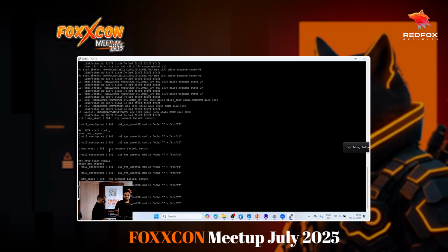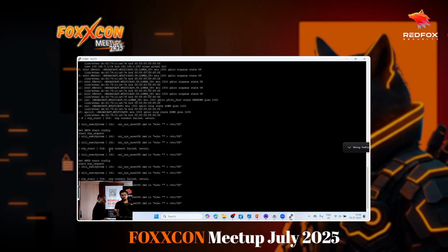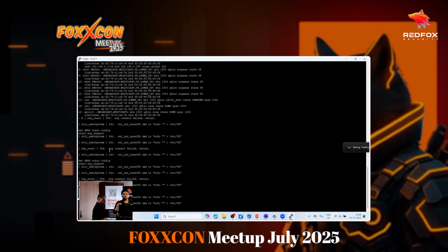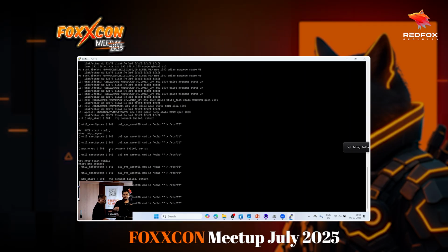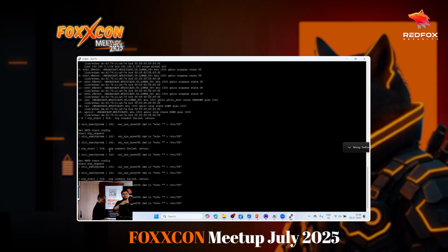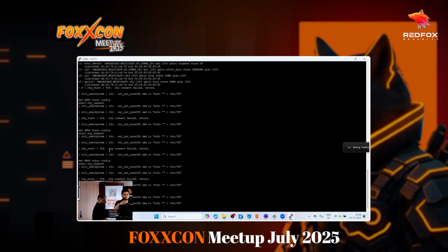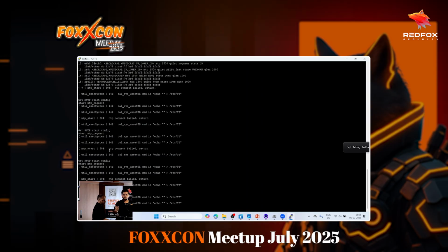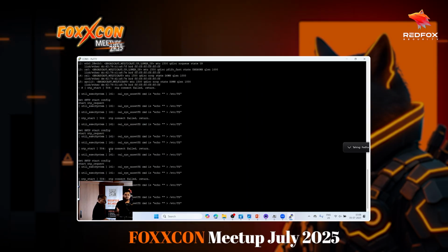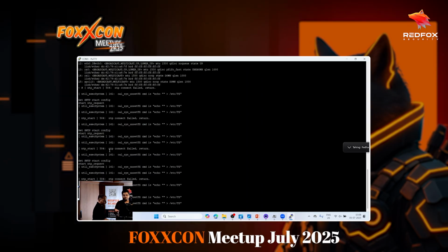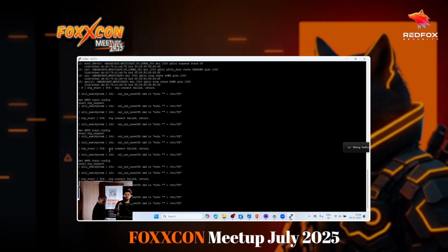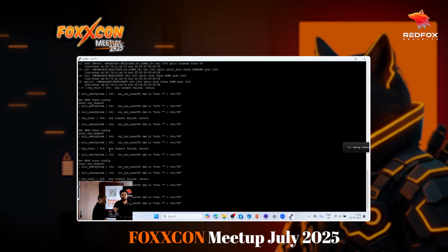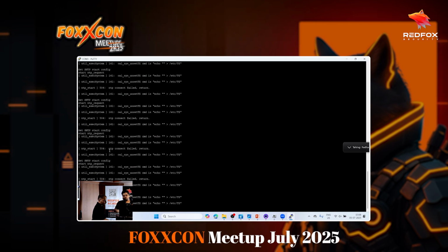Generally, to protect UART, there are protections that you could put in place. There is something called obfuscation that you could do here. When the kernel loads, it loads an obfuscation module that obfuscates all of this traffic, so you are not able to decrypt that. Even if you get a command shell, what are you going to do if you don't get any data out of it, right? There are ways to bypass that, which we'll be discussing further down the line. But that's one of the things that you could do.